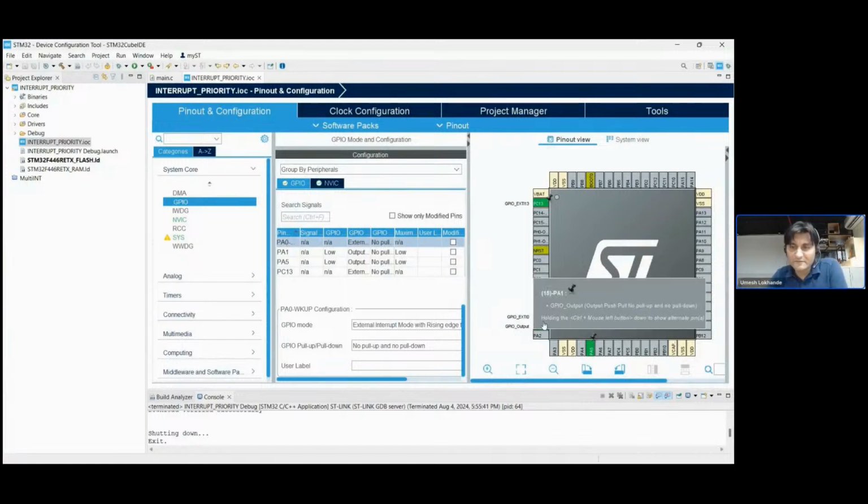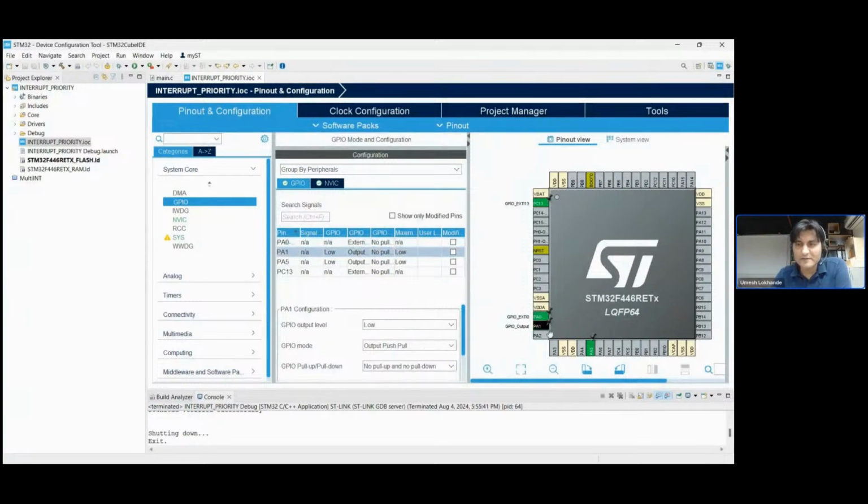And now you see this shows a blinking, and it says this is an EXTI interrupt 0. That's where our first switch is connected. Okay, that has to do with the green LED, and the green LED is connected to this PA1 pin. So when I select the PA1 pin, that's where the green LED is connected.